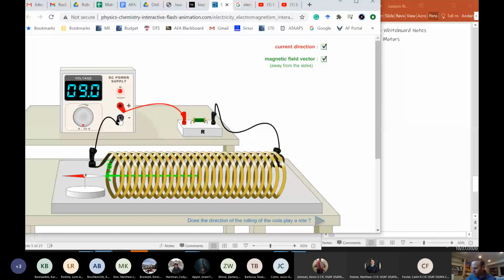If we reverse the current direction, then the magnetic field will go in the other way, and the plunger would go the other way. Okay, so solenoids are used in magnetic or electric door locks, in your car to engage your starter motor to your flywheel, things like that.